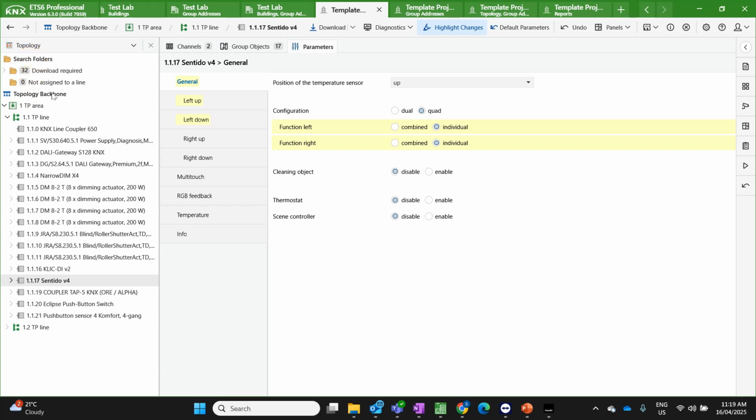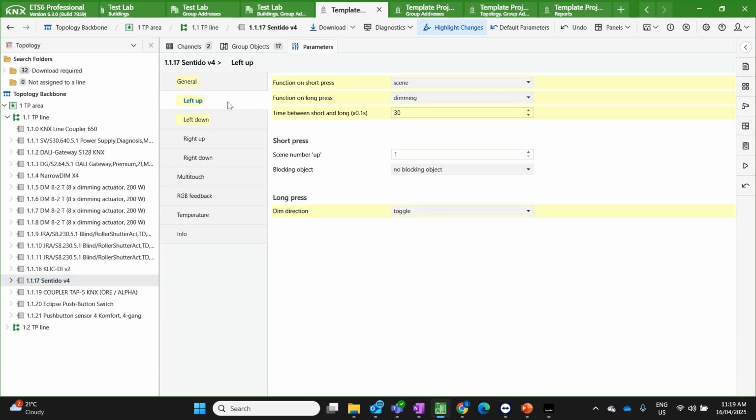So the first part of looking at this is the dimming part, and in my opinion, there are two particular switches that do this particularly well. It has previously been possible to do, but this has made it much simpler and easier. The first one is the Basalte switches, and they have this ability for you to choose a short push and a long push. The defining part is that you can call the scene on a short push. So the customer walks up and presses the scene.